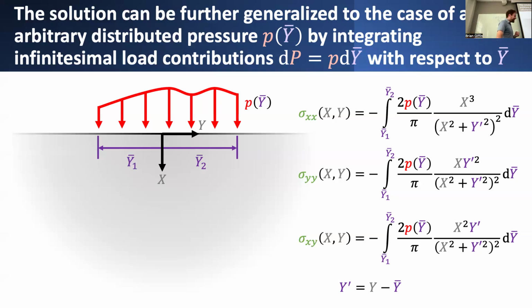I'll ask this then. Have you ever had to, for the purpose of designing a foundation, figure out what the stress is underneath the soil of a building? Basically, you want to know the distribution of stresses in the soil so that you're not going to incur some kind of failure underneath the structure. So how did you determine the stress at any point underneath some kind of building footprint that's loaded over some planar area? Multiplied by the depth. So the vertical stress.